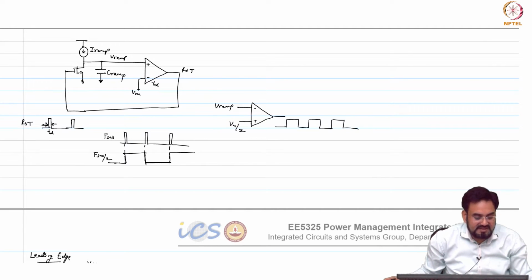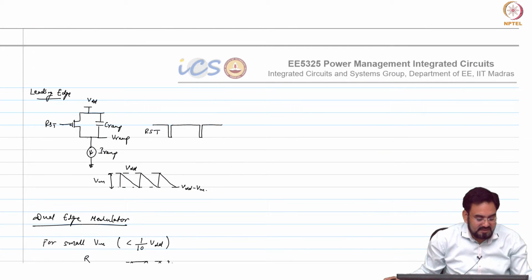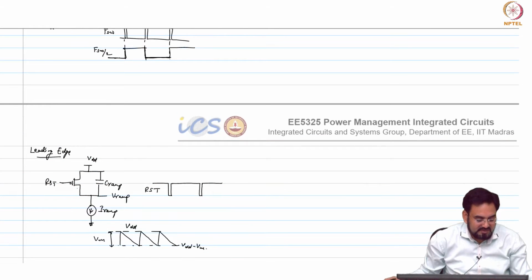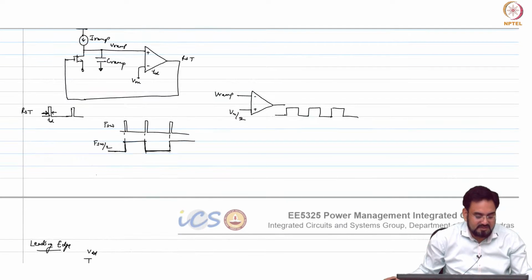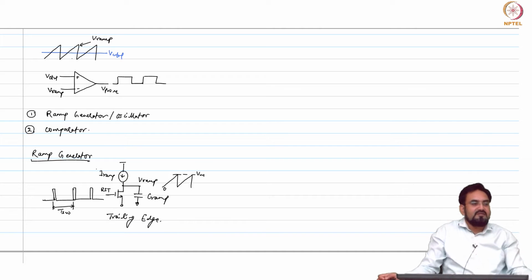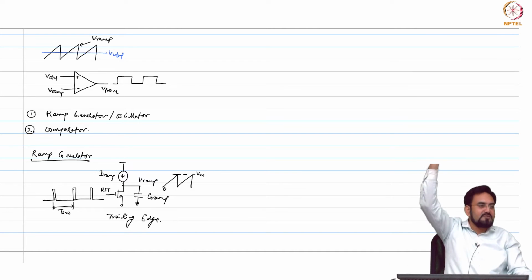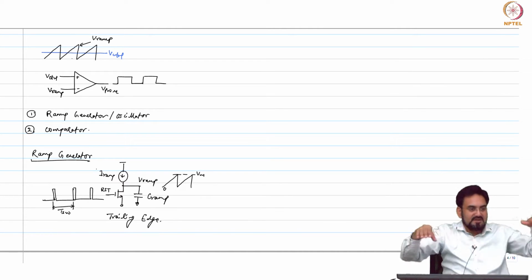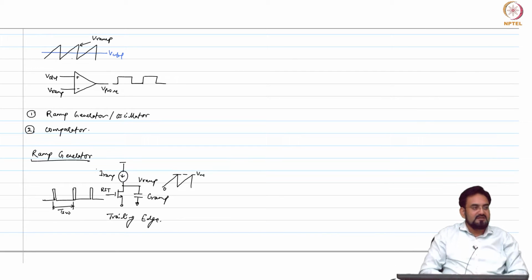In this oscillator, this MOSFET will reset to 0, ground, and again if you talk about this leading edge, set to VDD. So you are always starting from 0 or VDD in this case. So your ramp is shifted towards VDD or towards ground. Your ramp common mode is not at the mid VDD. So this may have a problem.